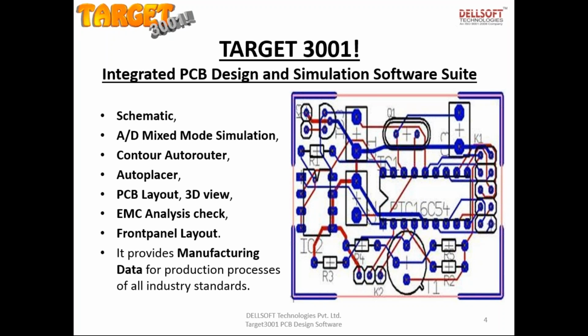So after the creation, we have AD mixed mode simulation, analog digital mixed mode simulation. So after the schematic, we have to check whether our circuit is correct or not. So we go to the simulation and we do various analysis like transient, AC analysis, DC analysis by changing the parameters of timing, simulation timing, and parameters of components. We see the analysis of that circuit.